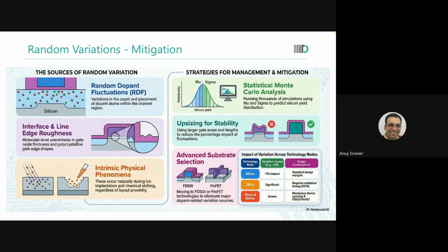So there was one question of that which of the following statements are true. So one option was random mismatch cannot be eliminated, and this has been marked as false. So we eliminated the random mismatches linked to random dopant fluctuations. We discussed that in the class. Just eliminated the random dopant fluctuation by using FDSOI. One impact. So see, what it meant was that there can be some parts of random mismatches which can be eliminated. Random mismatch cannot be eliminated. So it is true, right?